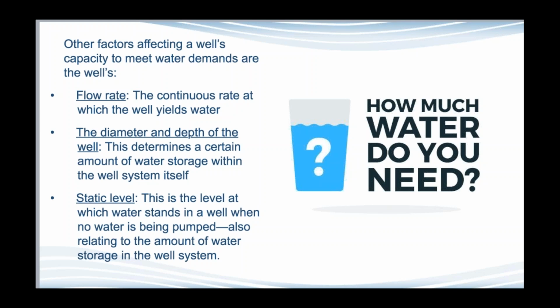That's where we talk about your storage capacity. In, say, a 5-inch well there, you would have 200 minus 12 be how many gallons that you would have sitting there within your storage capacity to be able to use properly. If you're a water table well, those are more like your dug wells or your very shallow drilled wells, in which your storage capacity is literally going to vary based on the seasons, and so is your static water level, as to how much rain you've had.